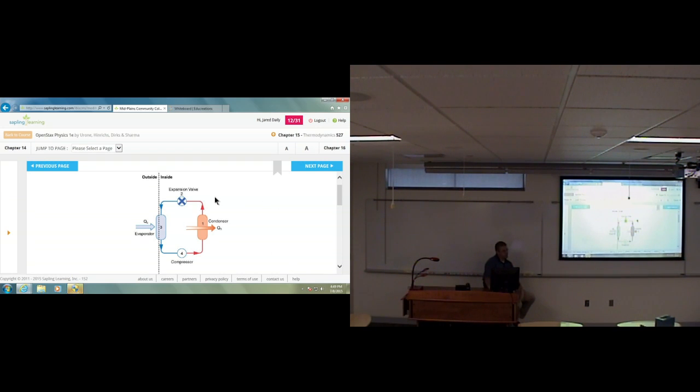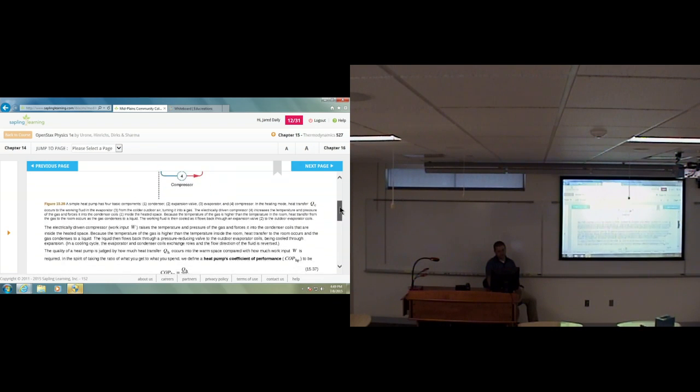of air conditioners. Freon is a liquid that evaporates at very low temperatures, that is a gas normally at normal air temperatures, and it's a gas at very cold temperatures. But if you force it to become a liquid by condensing it, using a condensing pump and a condensing system, you force it into a high pressure liquid, and then you take it into that cold environment and let it absorb heat inside the refrigerator and expand into a gas, and then bring it out and condense it again, and force it to condense and keep doing that, you're going to cool down the inside of a refrigerator quite a bit as that gas absorbs that energy as it expands.